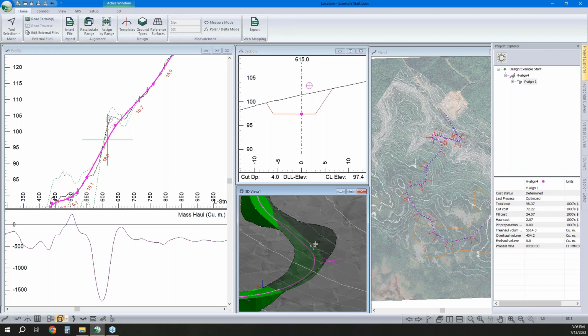So if we're looking at the center line of our prism here, if rain falls on our road, well, one, the roadway is flat, so there's nothing pushing that water off to the side for us. And two, if it is a weak subgrade, well, it may rut, which traps even more water on our road surface.